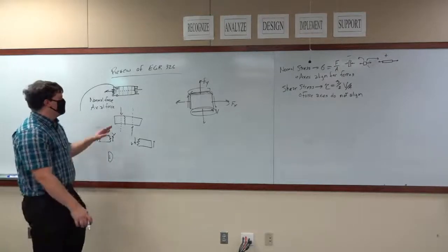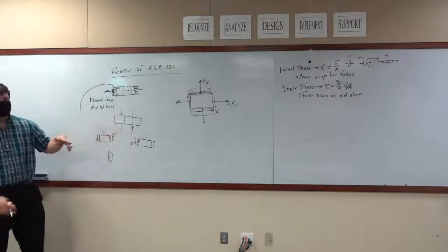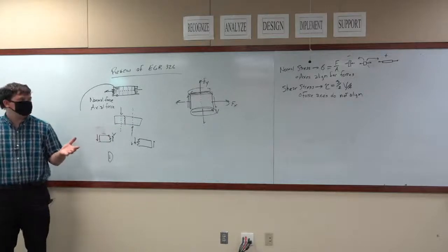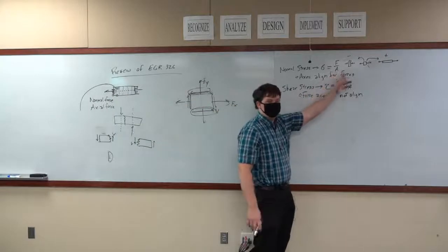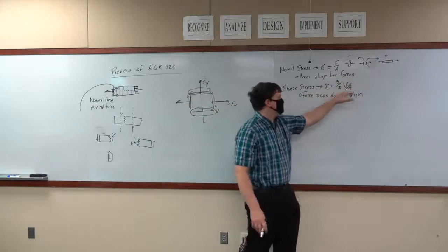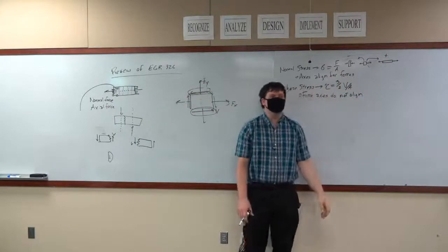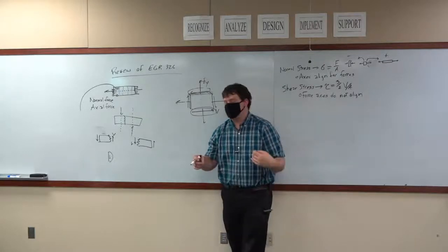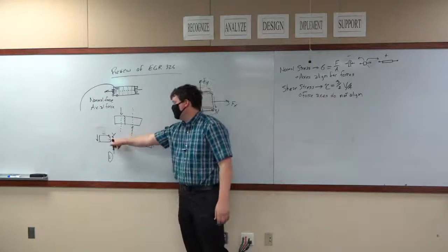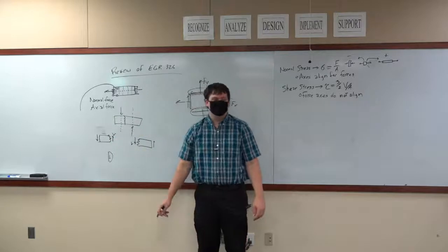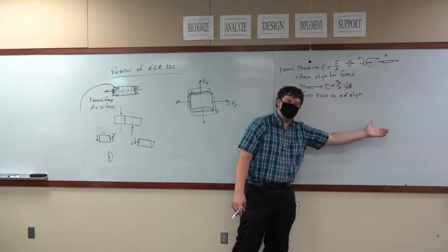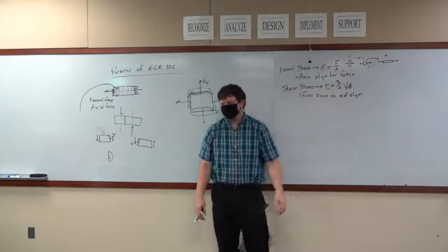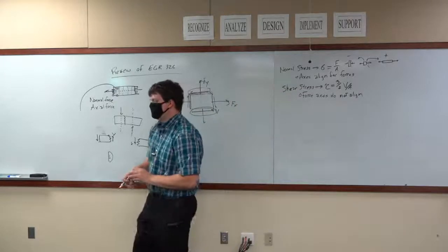Okay, but unlike this, the average shear force across that cross section would just be the force over the area. That's the average. But here, this now defines the maximum shear stress seen across the area, which is located right at the middle. So this is why this is 3/2 force divided by area. We're talking about maximum shear stress.